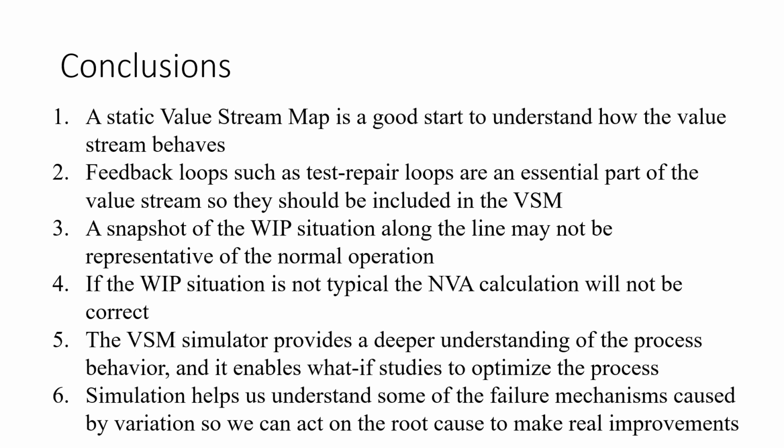These are some conclusions. A static value stream map is a good start to understand how the value stream behaves. Feedback loops such as test repair loops are an essential part of the value stream, so they should be included in the VSM. A snapshot of the WIP situation along the line may not be representative of the normal operation. If the WIP situation is not typical, the NVA calculation will not be correct.